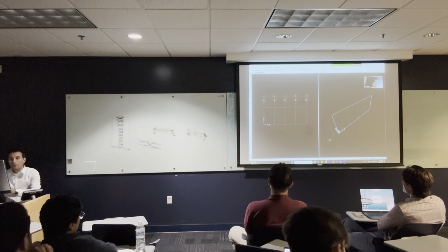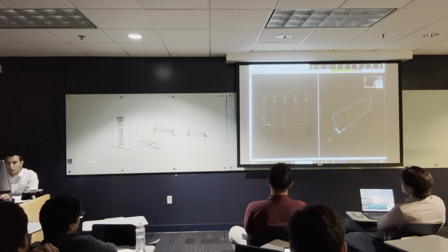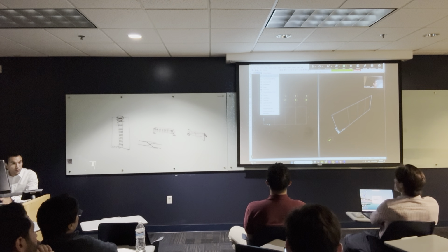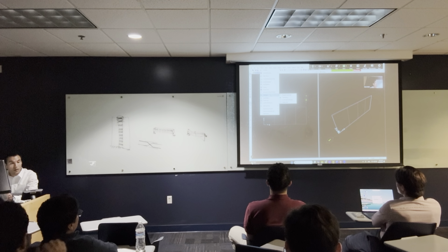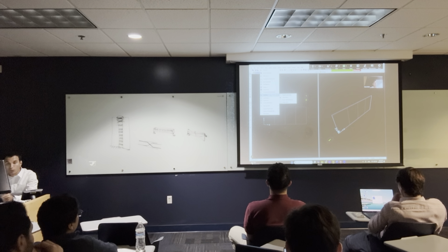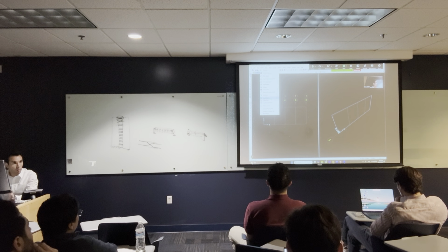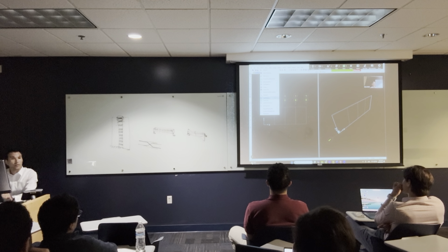First, I'm going to start by defining the material. There is a tab here called define. I'm just going to click on define, and you are going to find a lot of things that you can define. You can define materials, you can define sections. There's something called mass source, which we use for seismic design. There's something called function. If you have heard about the response spectrum for earthquake engineering, we define the response spectrum function here. There's also load pattern and load cases. If you want to tell the software that it is a dead load or a live load, we do all this here.